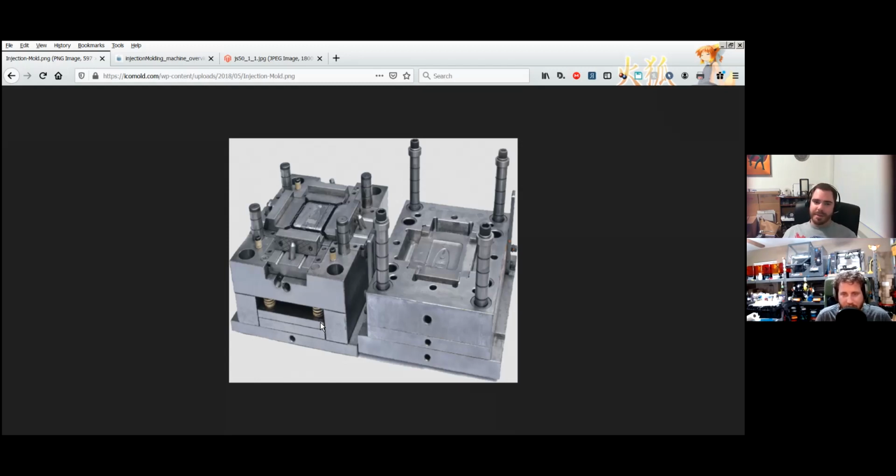Where I've seen it used is when you need extremely small features that you can't make an electrode for. So instead, they drop a very stiff wire in there, and little by little get out that material with EDM. Just discharge it and get rid of that metal.